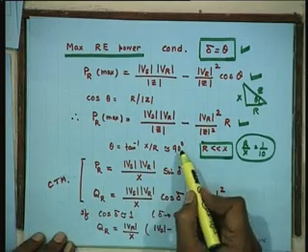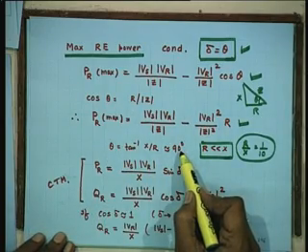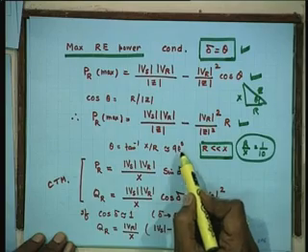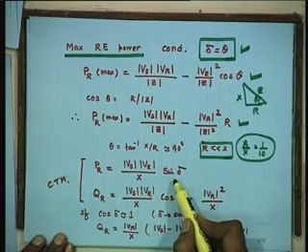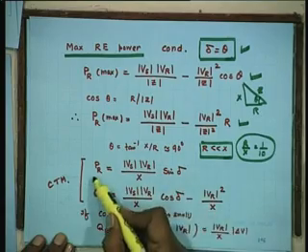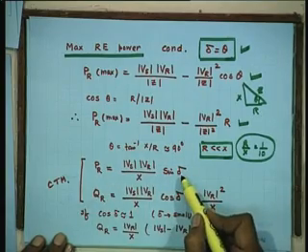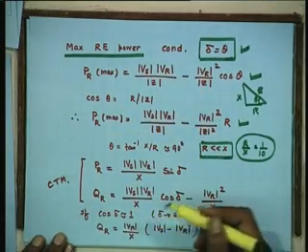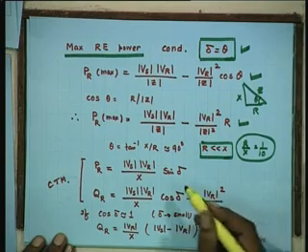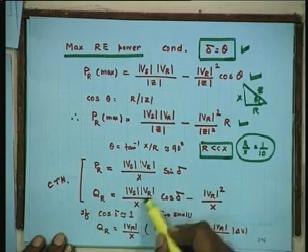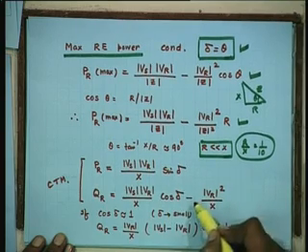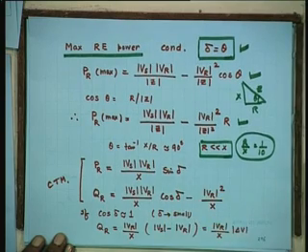If theta is 90 degrees, then what happens? Then PR becomes our good old friend Vs Vr upon x sin delta, and now if you maximize PR, delta becomes 90, what this young lady was saying. So, we have reached 90 finally, and for this QR is Vs Vr by x cosine delta minus Vr squared by x.